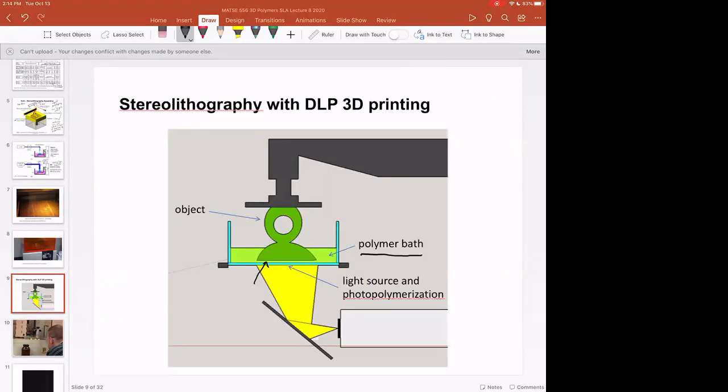Well, and that's 100% true. But the advantage of having, actually, this is a perfect image. So the reaction window and the black air there that you have, that's going to be a fixed distance. So your layer height is always going to be 50 microns or 100 microns or whatever you want. It's going to be dead on the entire time.